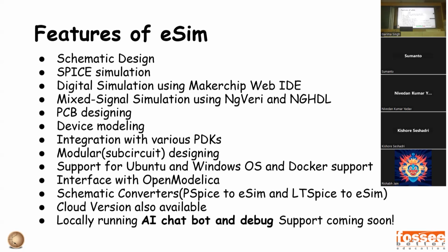We have integrated it with the SkyWater PDK, which is from Google, and also with IHP, work in progress for the GlobalFoundries 180 nanometer PDK. We support Ubuntu, Windows, and we have Docker support as well, and interface with OpenModelica, schematic converters, PSpice, KiCad to eSim.